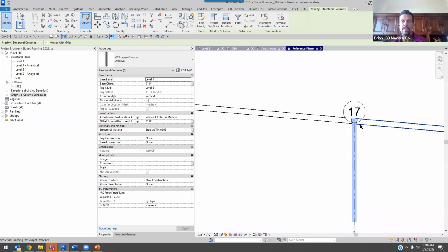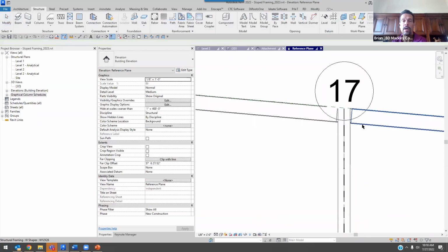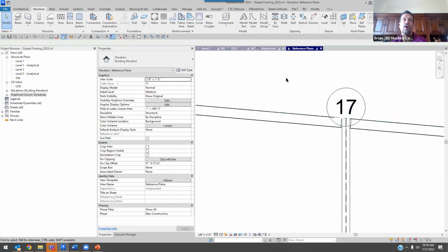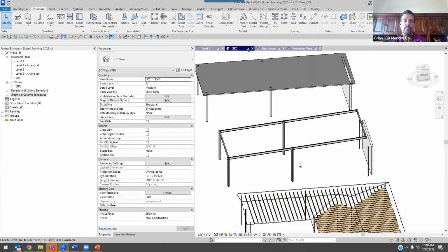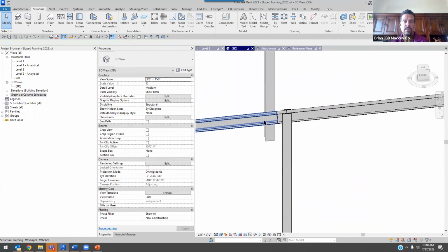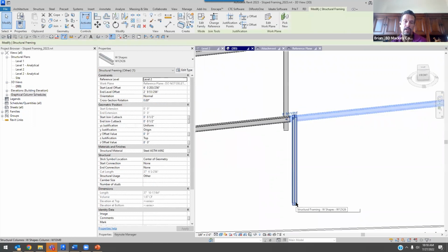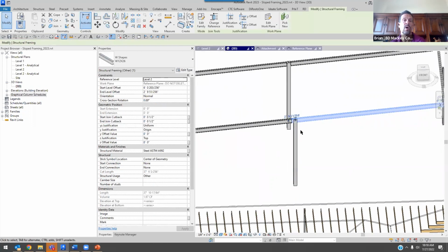And you'll see it does come through here. It does attach the column. And now my beams did become shorter because they understood that, oh, okay, here's my beams, I've got to go through and let the column reside through. Now, I did misclick on this side when I was doing it. So as I'm coming through and looking, it's like, ooh, I put those in there. But when I clicked the endpoint, I probably clicked the endpoint at the bottom and it was the wrong one. I believe this side I did midpoint. I believe this side I did endpoint.